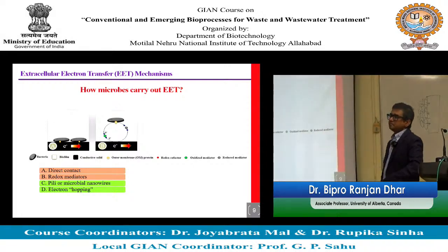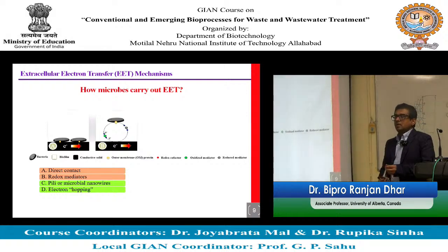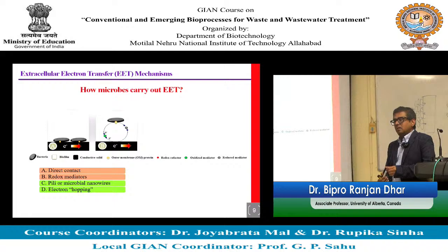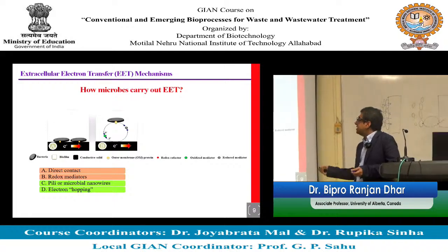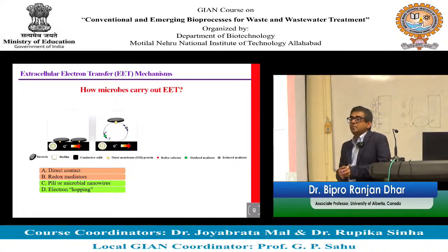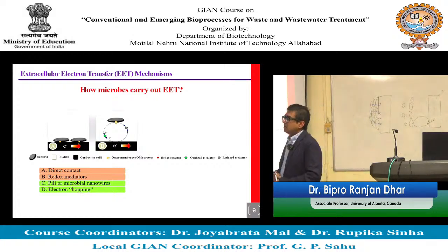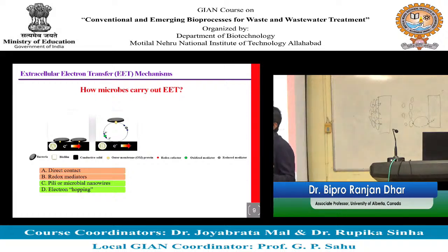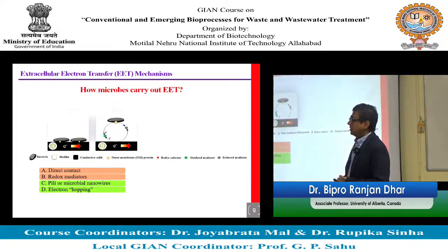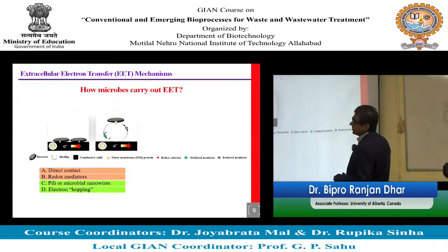Can you confirm whether pH has some kind of relation with this kind of mediator? These kinds of microbes prefer neutral pH. At low pH, even if some of these compounds are active, the microbes are not going to have any activity. That could be another challenge in wastewater treatment. So pH has to be close to neutral. Those microbes are very sensitive to pH.